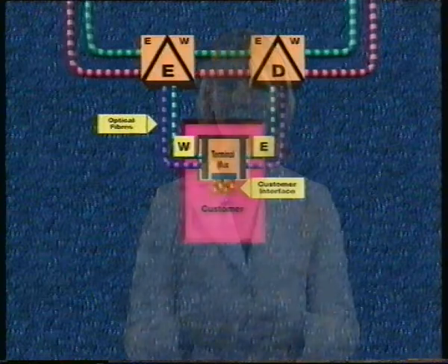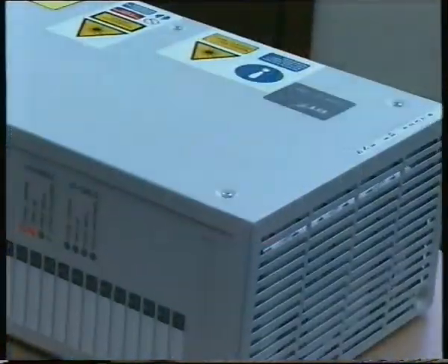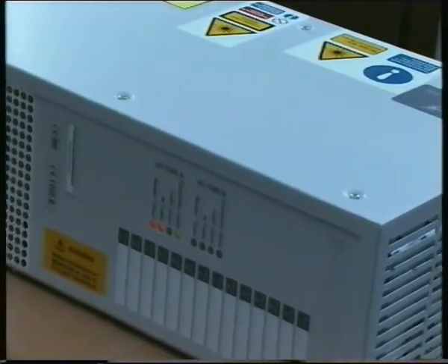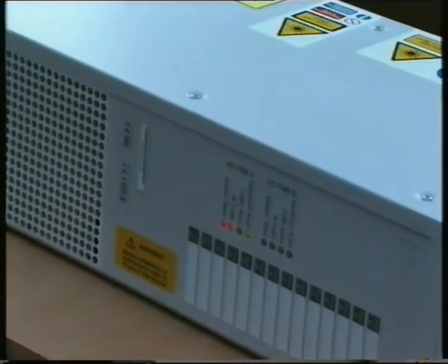The ADMs that we've looked at so far are very sophisticated pieces of equipment, so cheaper alternative methods of delivering SDH to customers have been developed. This one is known as the Marconi SDH extender and was formerly called the Virtual Container Transport System, or VCTS for short. This can be used where the full STM1 payload isn't required.